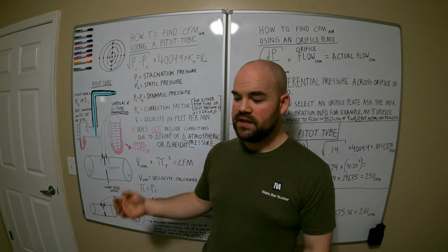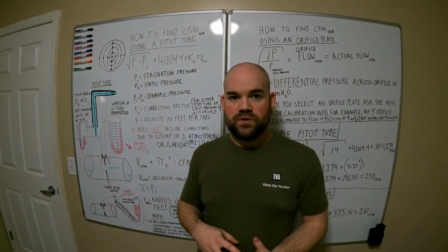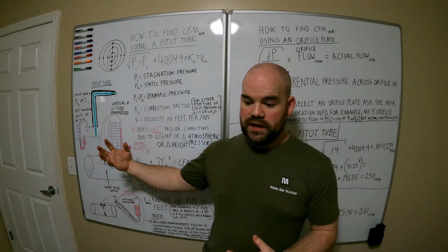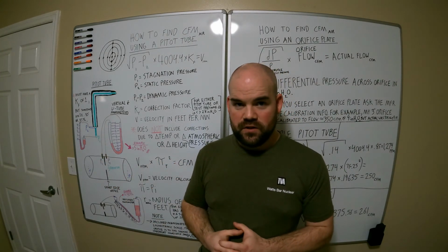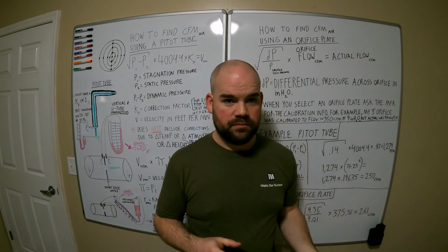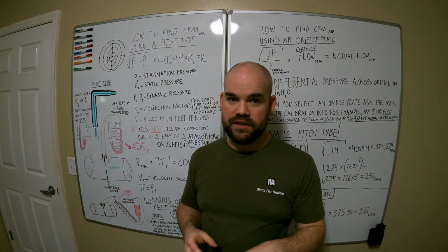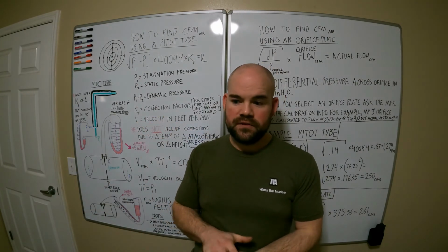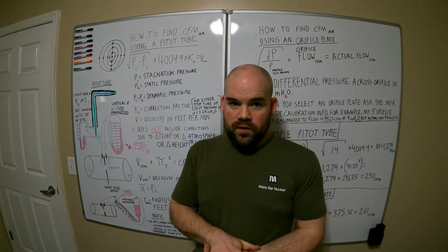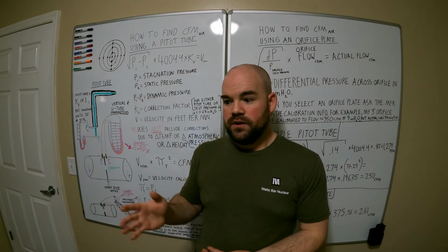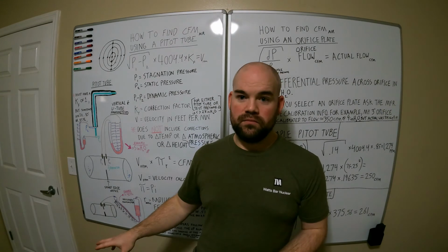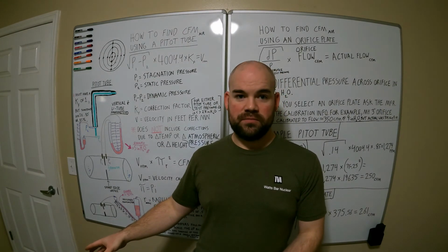So that's why turbos and such use a cold air intake and an intercooler. You want the air to be as cool as possible when it enters the compressor, then you want to chill it back off before it goes into your intake. My supercharger doesn't do that. It's right on top of the engine, okay? So water methanol injection or E85 fuel is how roots blowers make just as much power as a turbo application.